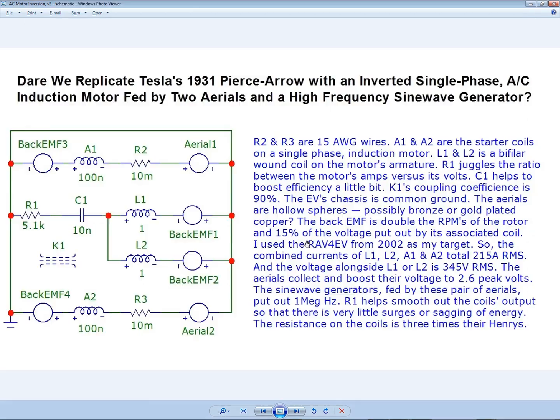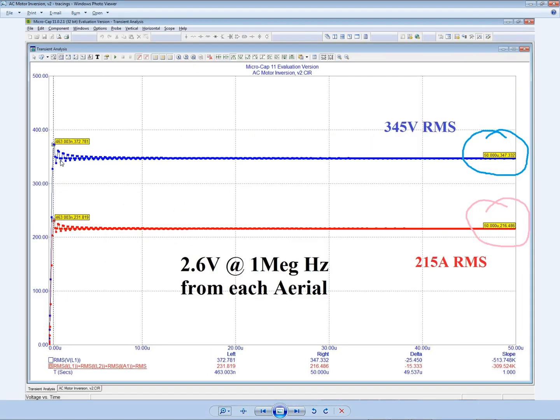When this R1 resistor I had taken out, when it wasn't here. But when I put it back in, because I was trying to find ways of balancing the circuit and increasing its gain, a funny thing happened. Very quickly, the values rose to their intended goal, and they took very little time, let's say less than 20 microseconds, to significantly flatten out. That's all it took, and then we just get a flat line of RMS, or amps or volts.